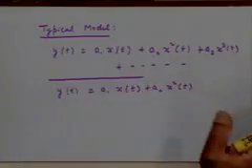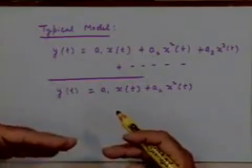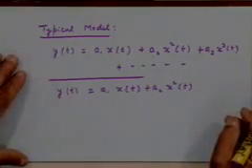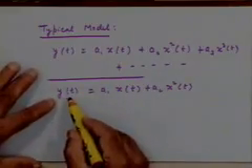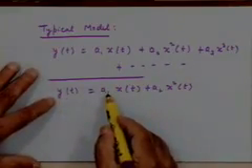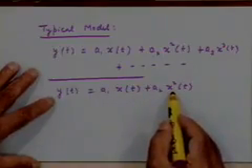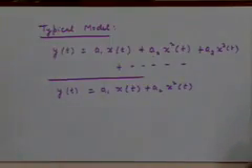Let me give an example. Suppose the input signal is a pure sine wave, just for the sake of appreciating this point, a pure sine wave of frequency, let's say, f1, right? Now what are the components present here? This will be (a1 cosine 2 pi f1 t) plus (a2 cosine 2 pi f1 t) whole square, cosine square, right?